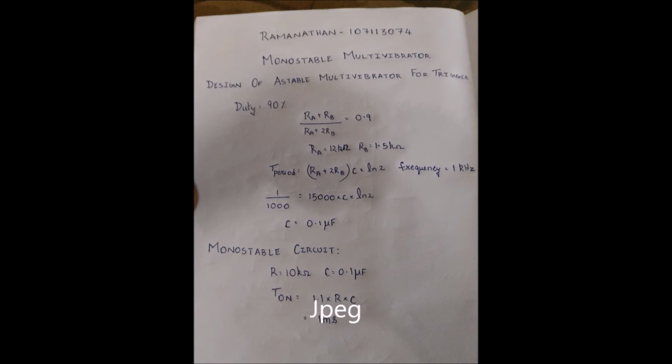Alright, let's design the astable multivibrator for the trigger input. Since its duty cycle is 90% and plugging in the standard values of resistors available, RA is 12 kilo ohms and RB is 1.5 kilo ohms. Now using the time period formula, we calculate capacitance as 0.1 microfarad for the input frequency of 1 kilohertz. Now coming back to the monostable circuit, we are using a resistor of value 10 kilo ohms and a capacitor of 0.1 microfarad. This gives us a T on of 1 millisecond.